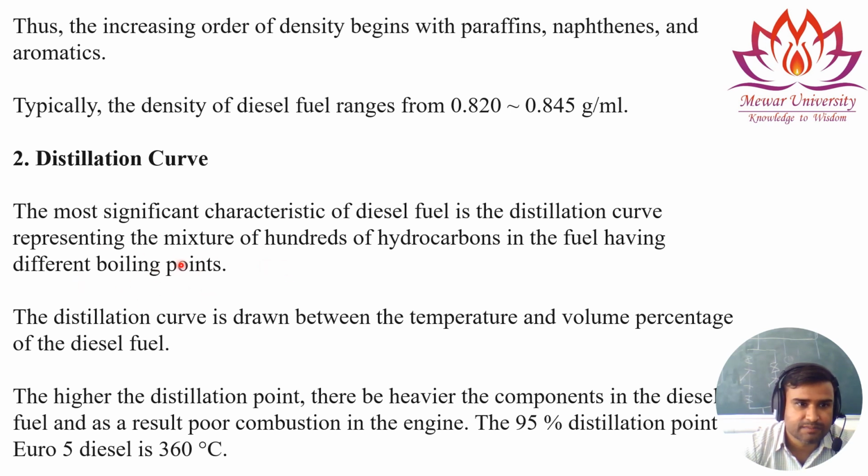So the distillation curve basically represents the multiple components present in the diesel. The distillation curve is drawn between the temperature and the volume percentage of the diesel fuel. The higher the distillation point, the heavier the component in the diesel fuel, and the result is poor combustion in the engine.